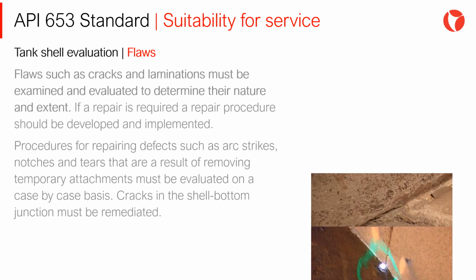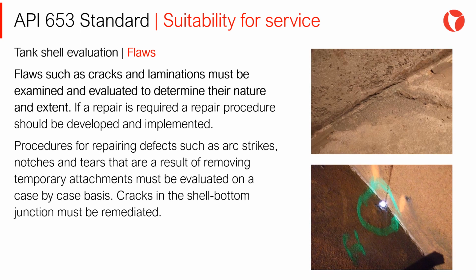Regarding flaws, such as cracks and laminations, these must be examined and evaluated to determine their nature and extent. If a repair is required, a repair procedure should be developed and implemented.